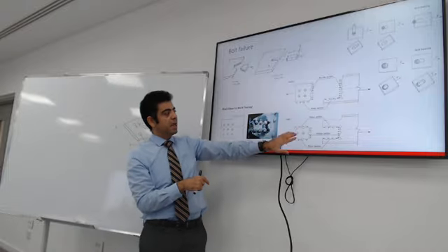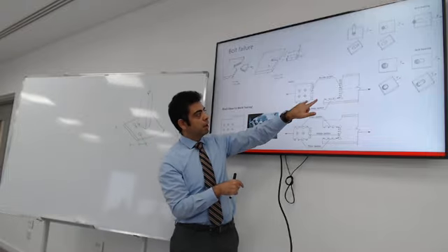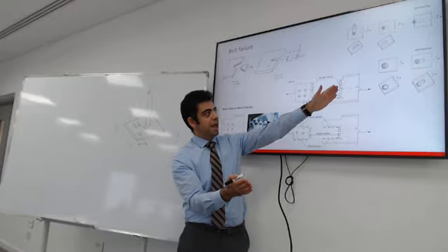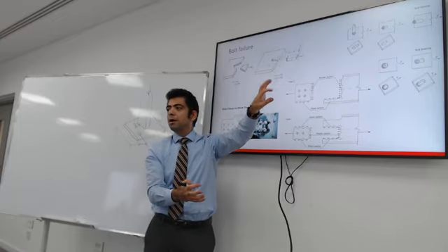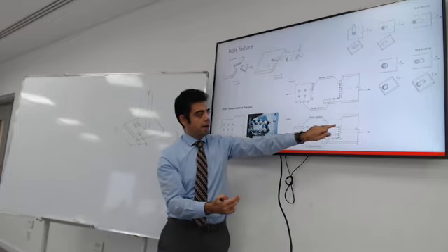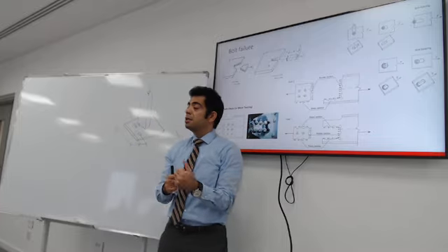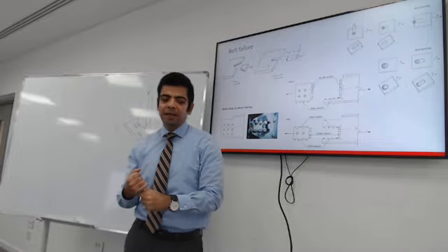So this is a case where the block will tear on the bottom side of the block or the group and the end side and will cut the beam clean, or it will just rupture around the block. And the code actually shows us some example of cases that needs to be taken into account.